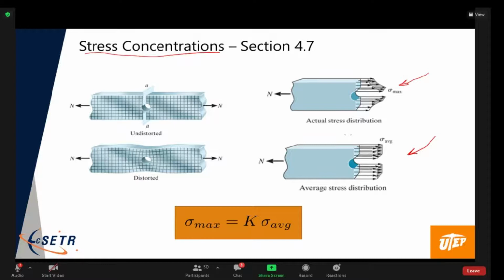The stresses will actually be higher at noon and 6 o'clock on the hole. You may have noticed this in that finite element project where you applied the bearing stresses; you had higher stresses in the same orientation on that bracket. Another type of stress concentration was where the tapered section met the base plate.